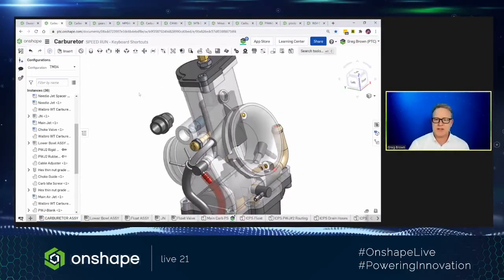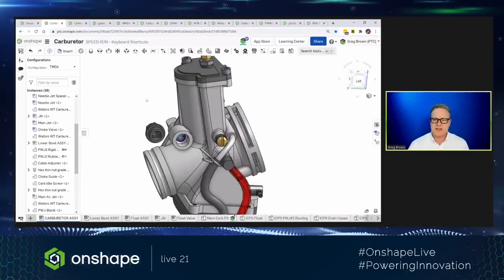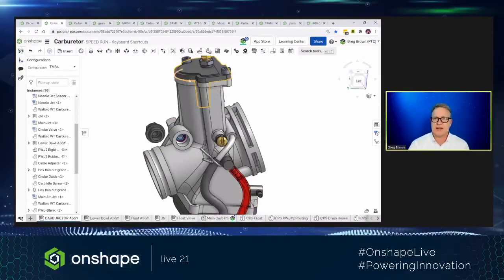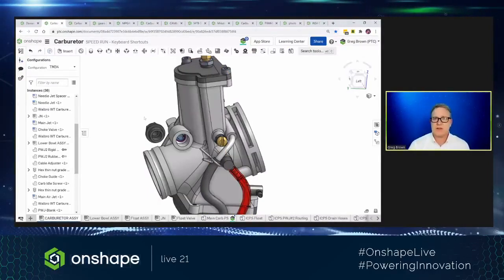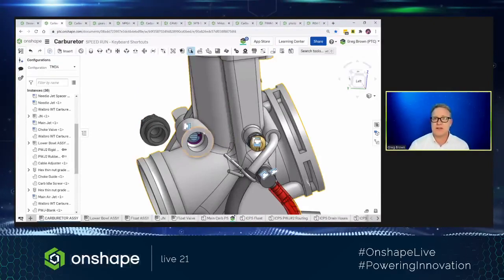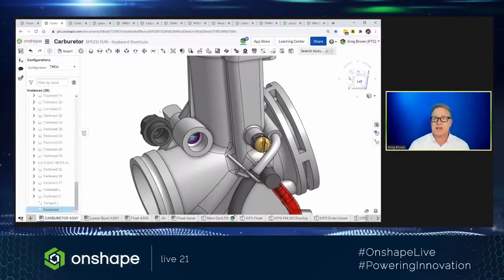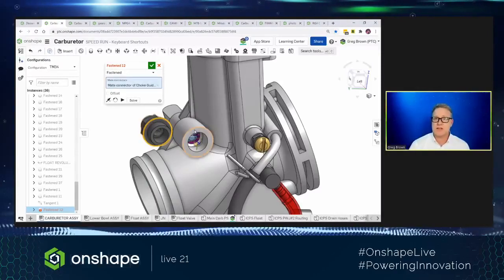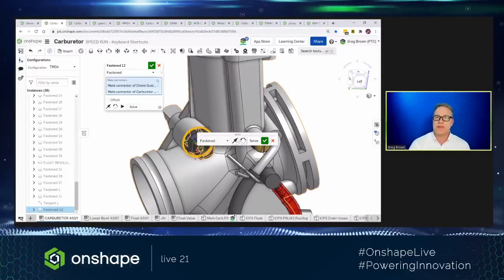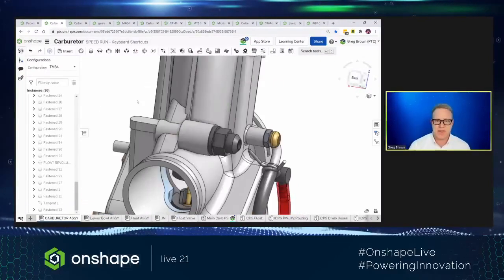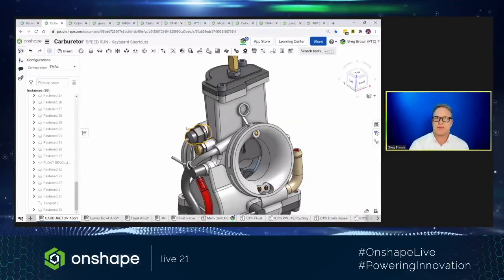I also use a bunch of silly mnemonics to remember the keyboard shortcuts. One of my favorite ones is, why are you there? And that will hide a part. The other one would be, hey mate, to show the mates. And if you're ever doing an assembly, assembling things together and things seem to be flipped, then you just yell out, ah, which is the A key, and it will flip it on its axis. So go ahead, experiment with those sorts of things.